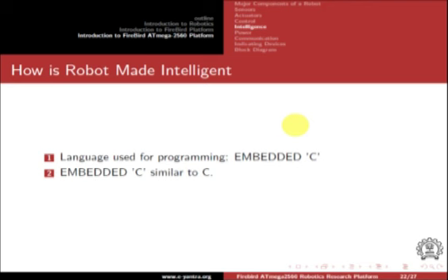Also, the code we write in C language is not understood by the machine. So we have to convert the code into a machine language, which we will call hex. We will learn how to compile code, generate a .hex file and load it into the microcontroller's memory when we start writing the code. A reference note is given in the documentation DVD with the video tutorial, which explains the process. We will see how to write code in another tutorial.